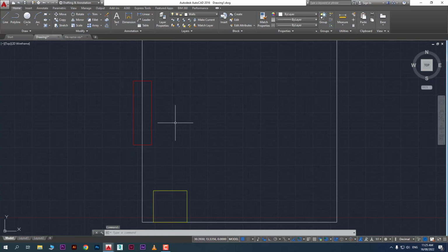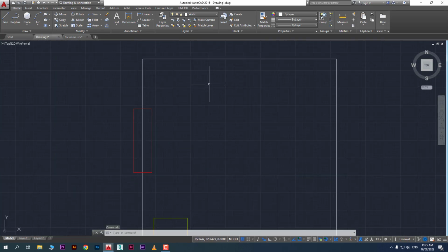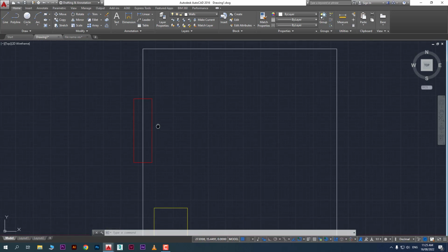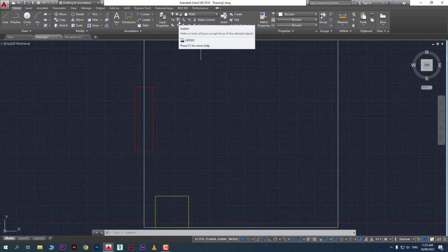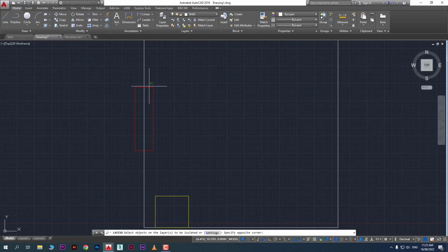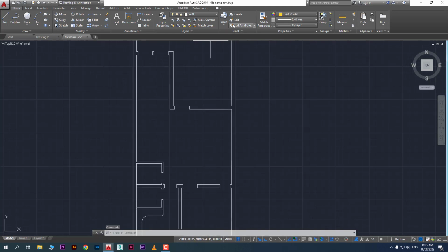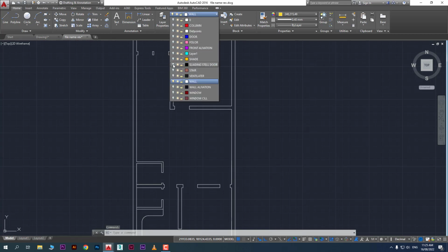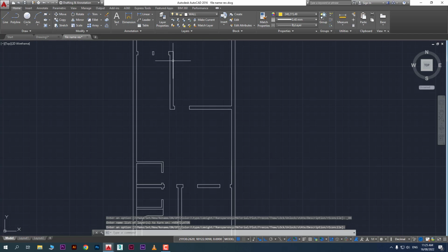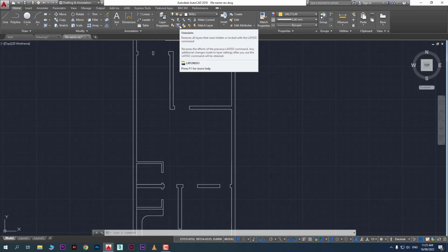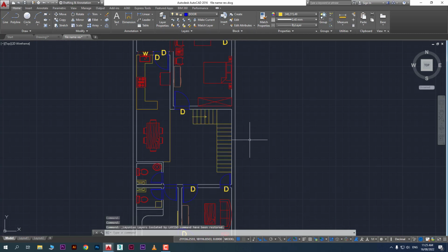Alright, for example, you selected the switch and then you click on the layer. Here I want to isolate the windows. So you take this switch, isolate, click on that layer and enter. That layer will be isolated. If you want to see what actually happened, it switches off all the other layers. Look here, all layers have been switched off, only the layer which is isolated is on. You can do it one by one also, but it will take time. Here we have another switch called unisolate. When you click here, all layers will be switched on.